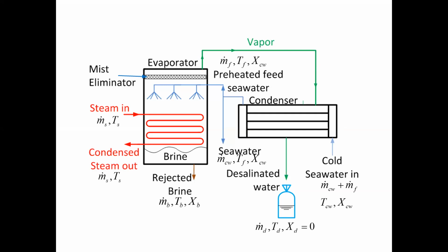These materials cannot withstand seawater at elevated temperature. Water enters at seawater temperature, which is a small value, but if the vapor comes on the shell side at high temperature, then it should be clean from salts. Otherwise it will affect the performance of the unit, which means that the materials are going to be damaged because of the salts.